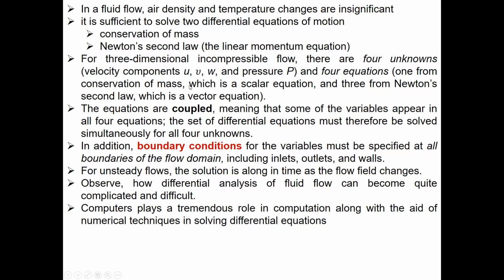One from conservation of mass, which is a scalar equation, and three from Newton's second law, which is a vector equation. Newton's second law, rate of change of momentum dp by dt, gives you the vector quantity. The equations are coupled here, meaning that some of the variables appear in all four equations. The set of differential equations must therefore be solved simultaneously for all four unknowns.